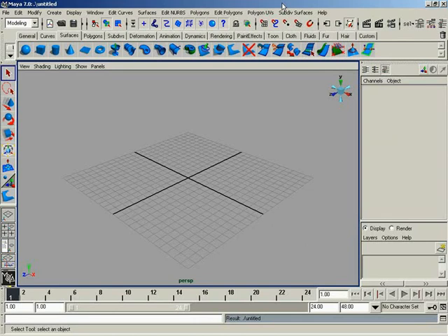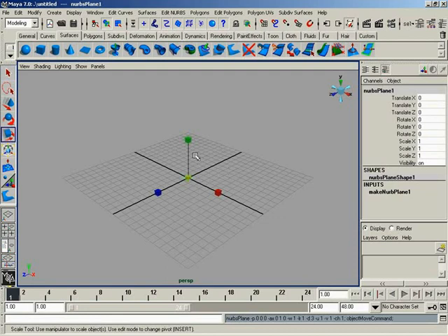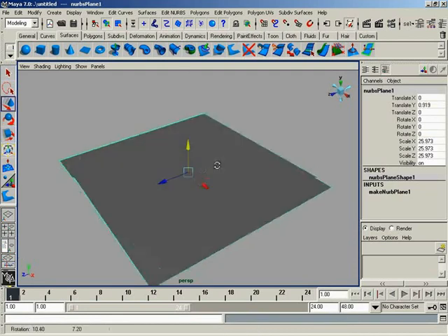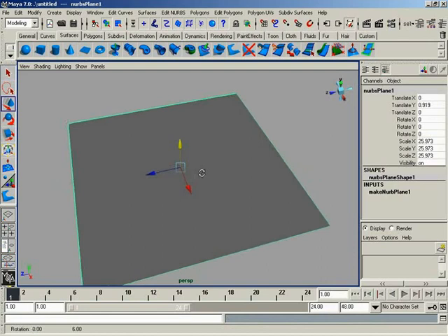Now, I'm not going to get too bogged down in the workflow issues of rebuilding. That's something that you're going to see in the workflow videos included with the NURBS modeling section. What I'm intending to do with this video is just to show you all of the various settings of the Rebuild Surfaces command, show you what each of those settings are intended for, and then we'll just move right along. So, for starters, let me create a NURBS surface, like so. And we'll move this up into the air, kind of get it away from the grid.